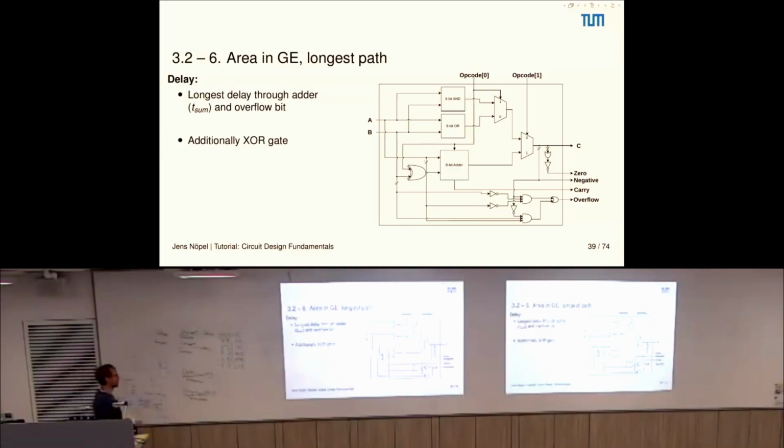Let's say maybe this is not the 3-input gate then, but this is the delay of your module, okay? You measure the delay of your module in that technology. And if you would do that, then you would also measure the delays that depend on that specific technology, right? And if you divide it by the NAND, then you just cancel out all the technology-specific delays and get a better feeling of what is the actual delay of your module.